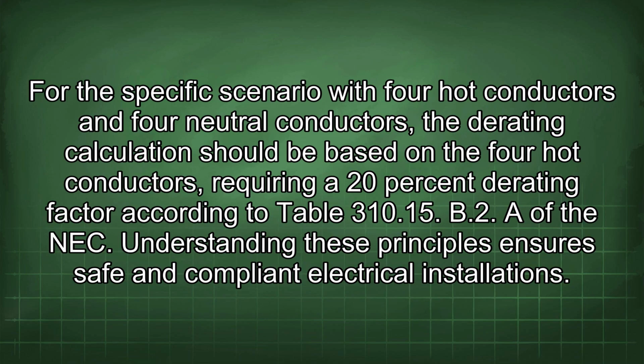For the specific scenario with 4 hot conductors and 4 neutral conductors, the derating calculation should be based on the 4 hot conductors, requiring a 20% derating factor according to Table 310.15(B)(2)(a) of the NEC. Understanding these principles ensures safe and compliant electrical installations.